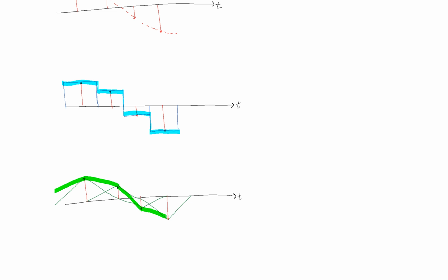That's all we're doing. Now again, this may be smooth or not. It has these corners, of course, so it's not the smoothest possible version of a signal through the samples, but it's smoother than the box one. And again, if these samples are close together, this will be a quite smooth representation. Now this one here was the easiest one to implement. This one is a little more complicated. It requires adding up these contributions in between samples, performing this interpolation.